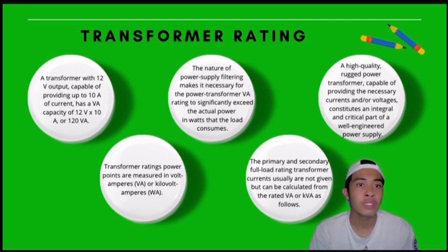Next is the transformer rating. Engineers rate power transformers according to the maximum output voltage and the current they deliver. For a given unit, we will often read or hear about the volt-ampere capacity, which equals the product of the nominal output voltage and maximum deliverable current.